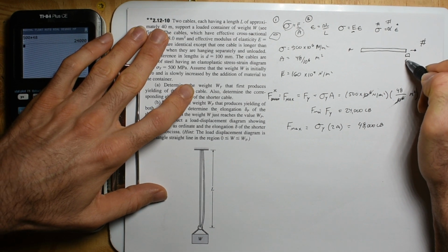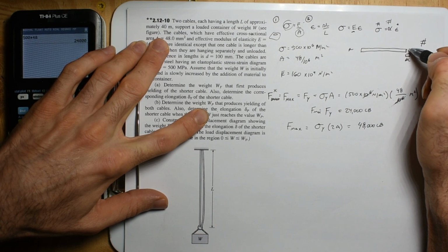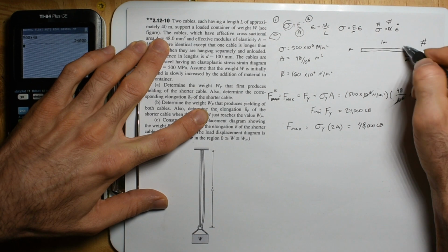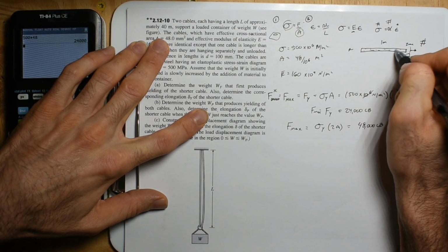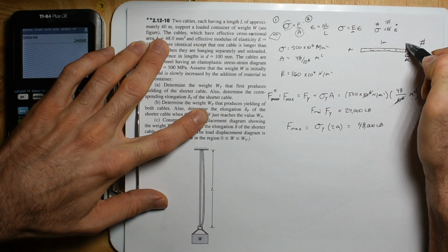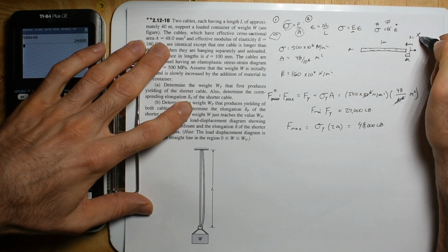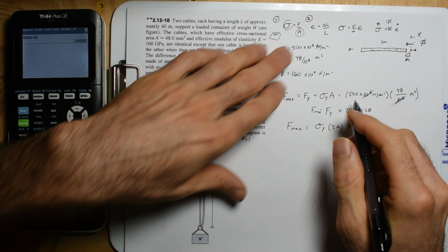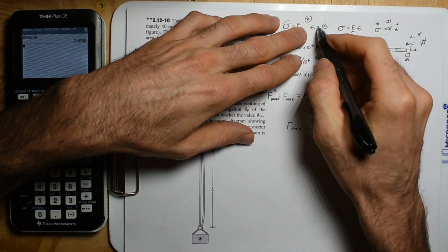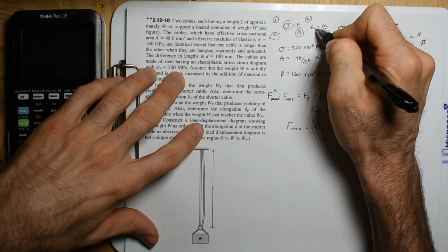But the change in length that we're most interested in is the elastic change in length. It's a point where if we pull a 1 meter piece of steel 2 millimeters, we can let go of the force and every molecule goes back to its original position. But pull it more, if this starts pulling more than 2 millimeters, it's going to pull like Play-Doh and break. So this 2 millimeters is mentally a high end. So let's see if we have enough to get what we want. This is a parameter of the material. This is what you put a subscript on.